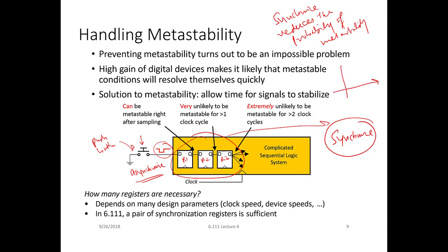And just to remind you what metastability was: if you had these back-to-back inverters, we saw that there was this curve for our buffer, and then we had this kind of curve for this feedback path, and we said that it intersects at 3 points. 2 of them are stable and 1 is metastable.